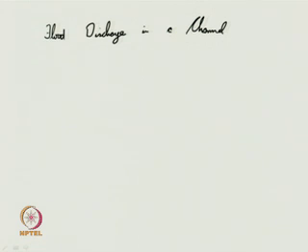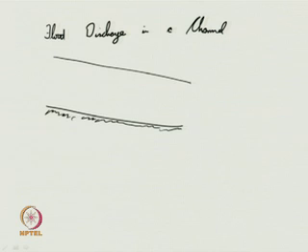You have to take a considerable reach of the channel. Earlier we were dealing only with one cross sectional area of the channel. Now you may need to take a considerable reach of the channel, and along the reach, wherever it is flooded or overflowed, you need to take into account how you can measure the corresponding discharge.